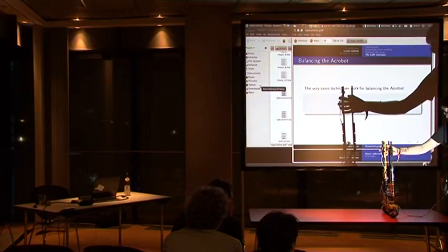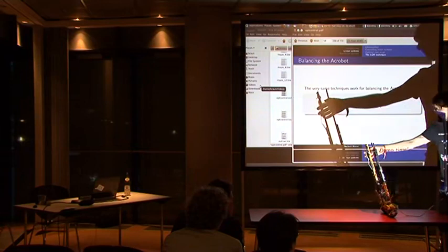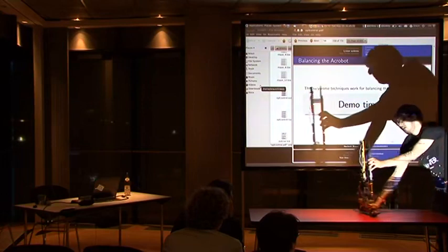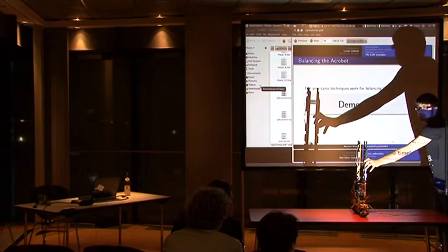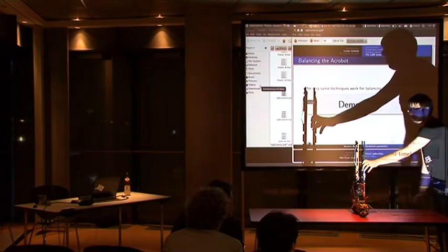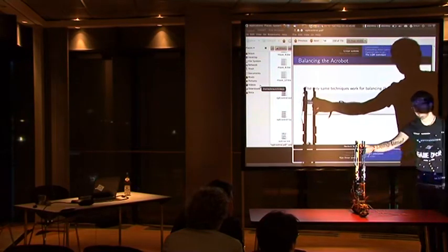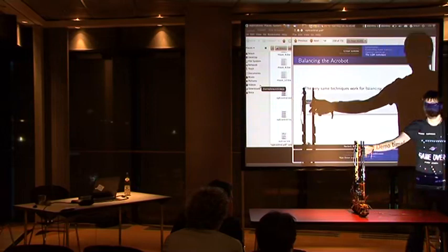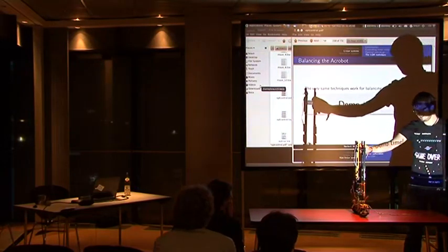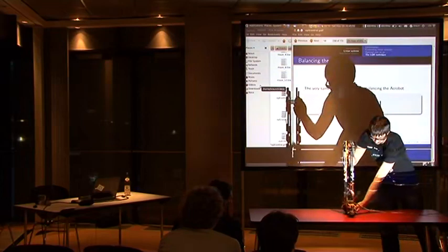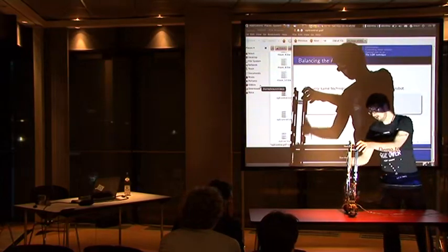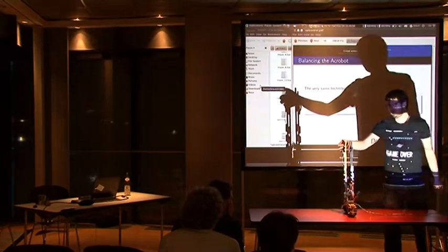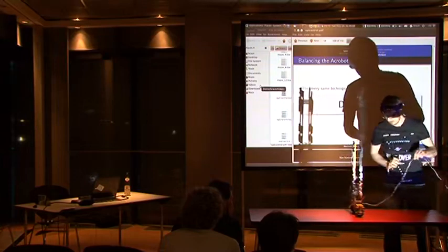If you just try to solve this as a PD controller or something, and it was like this. Now, how do you correct a deviation like this when you accelerate? And then it's like this. And it has no reason to ever slow down again, because now this angle is 0, so why should it slow down? So if you did this with a simple PD type of controller, it just drives into the wall on the one side or on the other side. That's no good. So what we need is to consider 2 degrees of freedom, and have it actually return after it balances this out. It has to return to the starting position, at least approximately. And that's that.